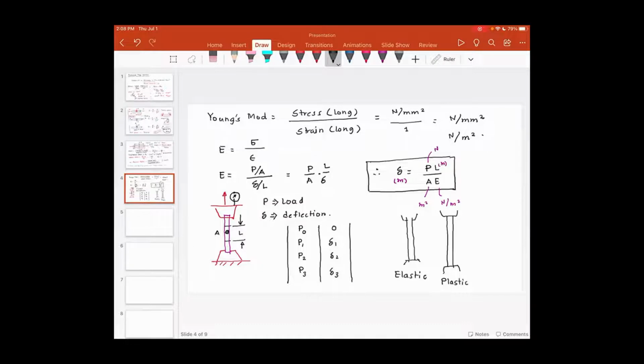And then what you'd observe is that the component gets overloaded and sort of coning appears. So the cross-section area starts getting reduced and there is a high level of stress in this necking area. And after some time, clearly the component fails.